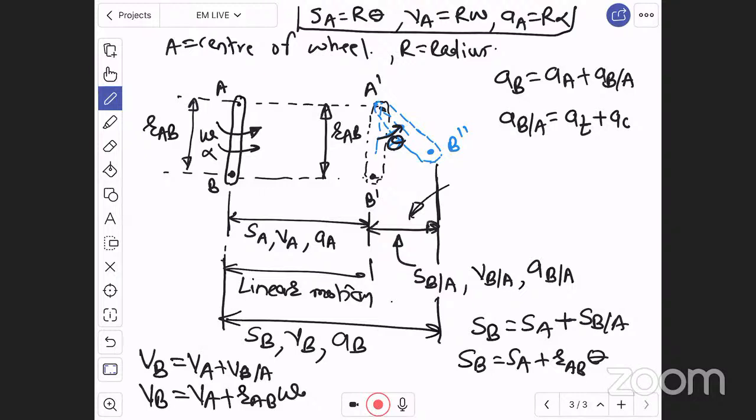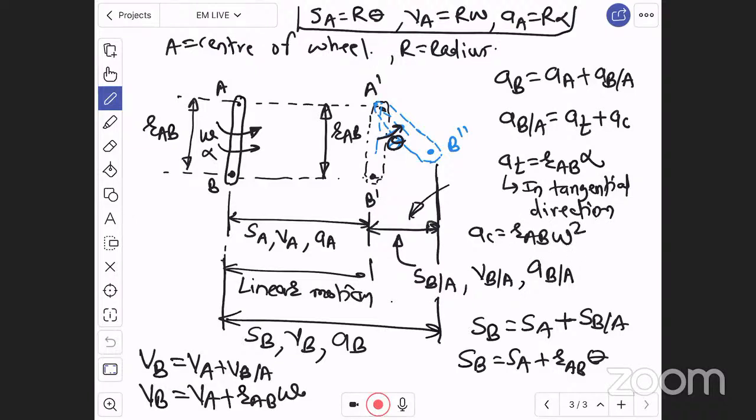इसके ऊपर मैंने 1.5 घंटे का लेक्चर लिया है इससे पहले के वीडियो में, लाइव लेक्चर में, वो आपको आना चाहिए. Now, therefore this tangential acceleration is nothing but RAB alpha. This also we have taken derivation देखा है previous lecture में. Tangential acceleration at B is RAB alpha and it is in tangential direction, right. And centripetal acceleration AC is RAB omega square.